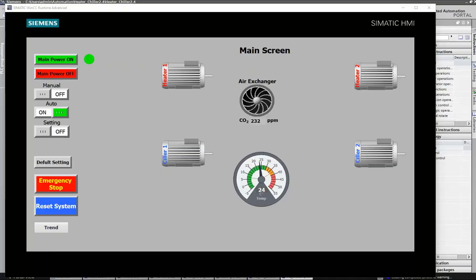To save energy and reduce wear on components, the air exchanger operates independently based on the carbon gas levels in the hull. It should activate if carbon gas levels exceed XX ppm and deactivate when levels fall below XXX ppm. Pressing the emergency button should turn off the system.